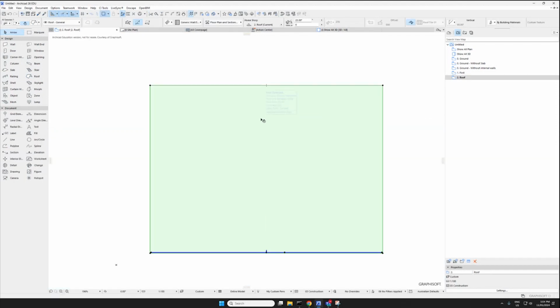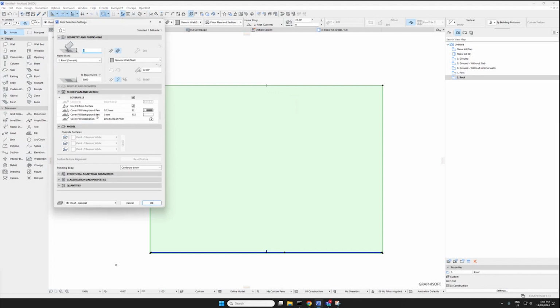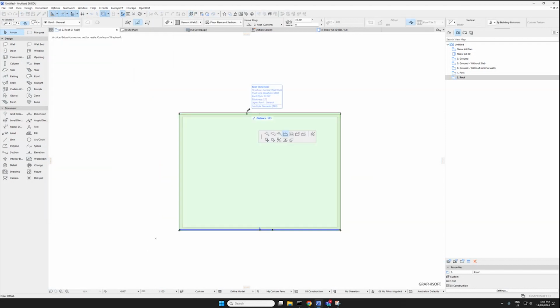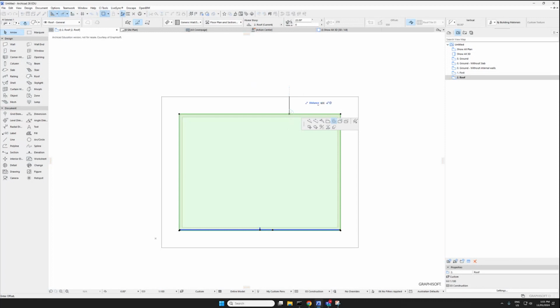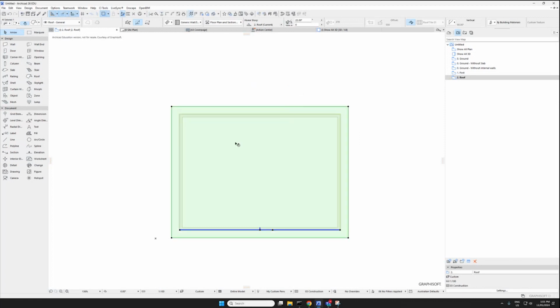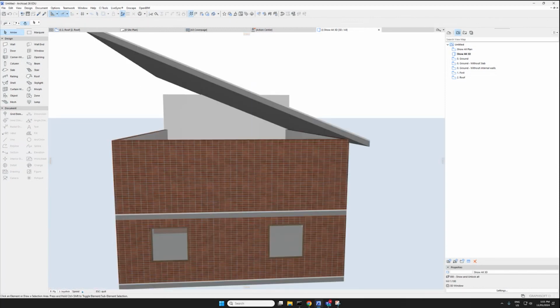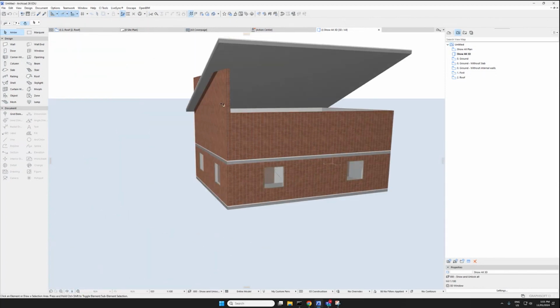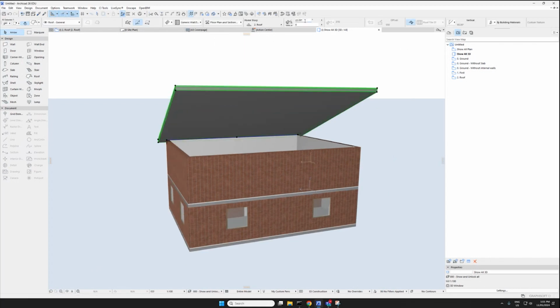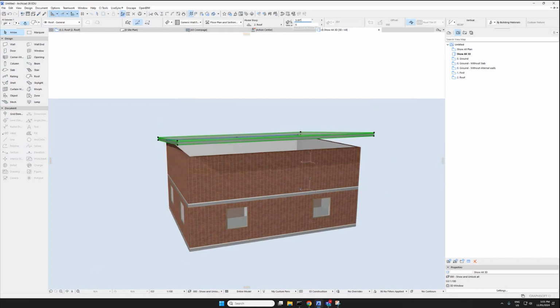And then I go Control T. I do not want the background pen. So line click. Okay, and then I want to offset that as well. The way you can offset it is either offset the edge alone or offset all edges. So generally you would have an offset of maybe 600, let's say. Press OK, then you can press F3. See, it looks a little bit funny. And we'll bring this one back down. Okay, I'll bring it down to, let's say, a 5-degree roof.